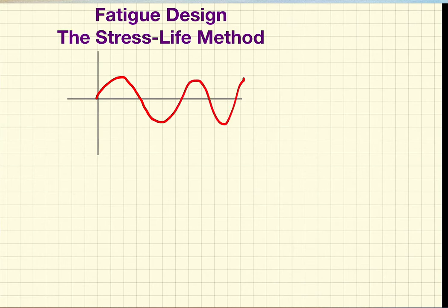So let's consider first the way that the stress versus time looks like in the simplest possible way. And the simplest possible way is fully reversed stress amplitude, and it looks like this, fully reversed, where on one side we have S, and on this side, actually not S in this case, to be consistent, this is the applied stress and this is the time.